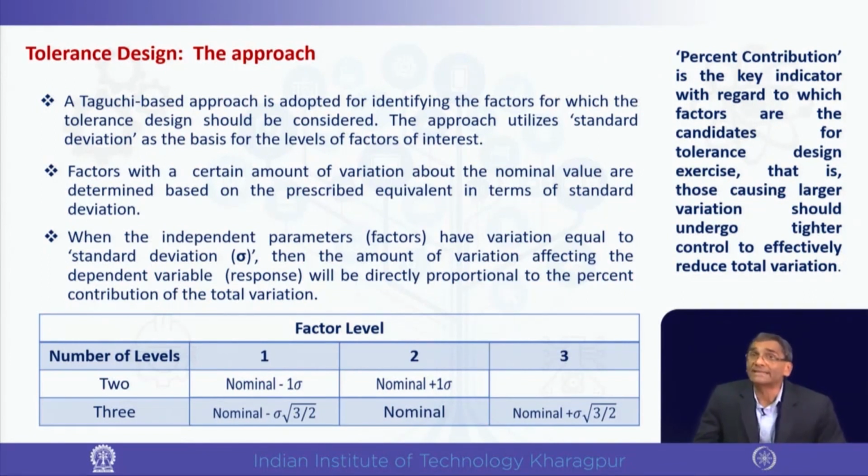Now, to assess the effect of variance, it is not exactly the USL LSL, upper specification limit, lower specification limit based monitoring and tolerance stacking. It is rather to check the effect of variance of the inputs on the final product, the output, and here our purpose is to mitigate that by adjusting or tightening the tolerance more specifically. To what extent should we tighten? That rationality matters, because making it too close may increase the cost and demand on resources, which perhaps is not so much required. So, what is the optimal level? How much can we tolerate? That is what we try to find out from here.